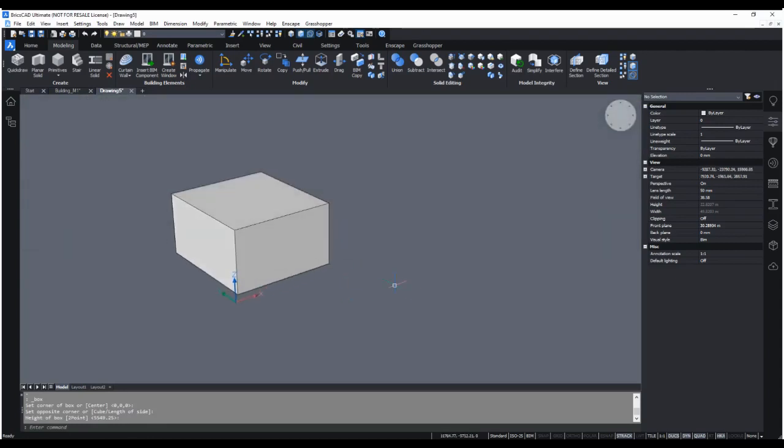Now when we hover the cursor over one of the faces, the quad displays as a single icon, which is the most recently used tool with this entity type. And if I click on that, we can see, in fact, it does say solid face now instead of no selection. If I want to launch the most recently used tool, I can just left click or move the cursor over an icon that I do want. So we'll just go ahead and use Push Pull, and now we can use the Push Pull icon.